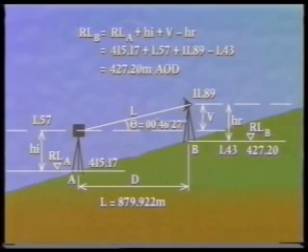No allowance has been made for the effects of the curvature of the Earth and the refraction of the infrared wave by the atmosphere. Although it is possible to calculate a correction for curvature and refraction, this is not recommended due to the difficulty in obtaining a reliable value for the coefficient of atmospheric refraction. Instead, the distance should be measured again, but in the opposite direction, as soon as possible after the first measurement, and the mean value used.